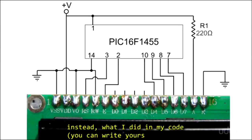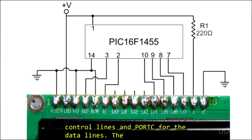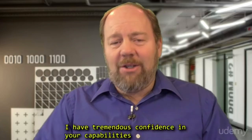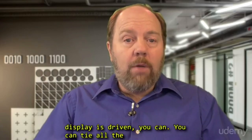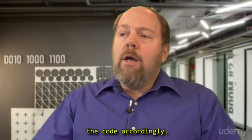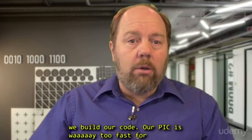But instead, what I did in my code, you can write yours differently, obviously, I used port A for the control lines and port C for the data lines. The schematic is in the downloads, as well as several code samples you can use. I have tremendous confidence in your capabilities at this point, so if you wish to modify how the display is driven, you can. You can tie all of the lines to port C, and you can just alter the code accordingly.